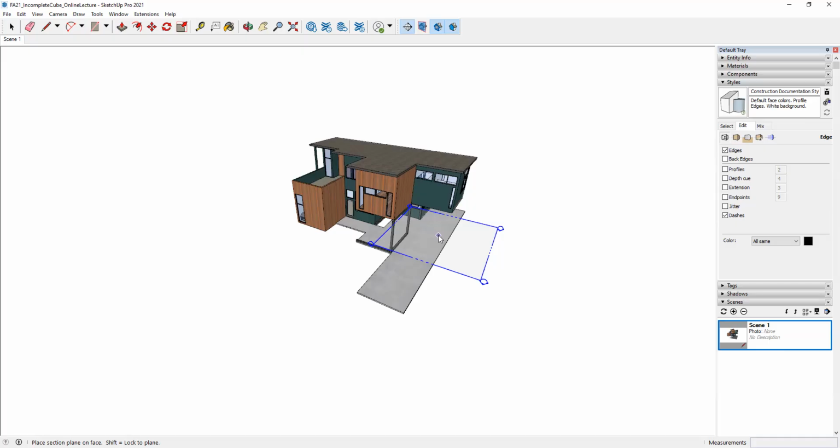After this, we're going to be doing reflective ceiling plans, and those are plans that are looking up. The benefit of that is that we can actually see the ceiling. That's important to know because it's important to know where the light fixtures are going to be placed. If we were to get into more detail, any protrusions, any detailing or architectural elements in the ceilings, or any vents, air conditioning, HVAC vents, different things like that would all show in a reflective ceiling plan, which is what we're going to be showing next.